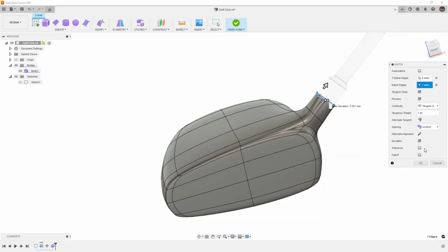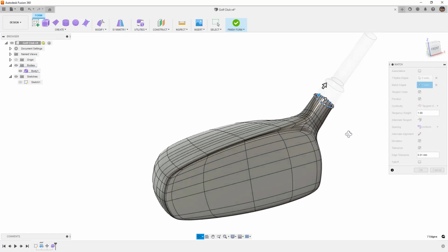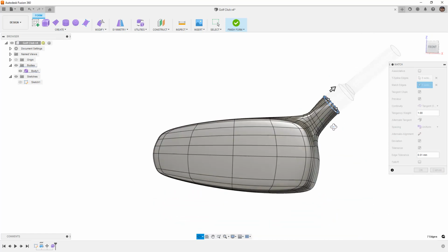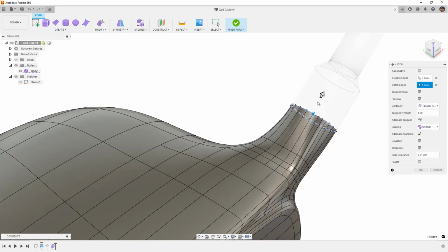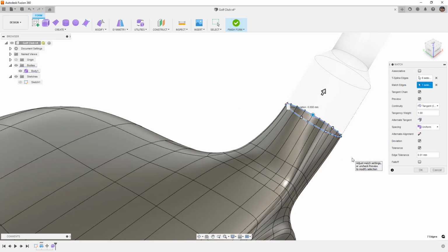We connect it with tangency. We can turn on tolerance, allow it to subdivide, and then we can be happy with the results. The reason that we need to think about tolerance is because in order to get 4 or 5 form faces to match a true cylinder, you need to have some sort of tolerance turned on. Otherwise, it's never going to match. And the whole intent of this is to go back into the design workspace and connect these things together.